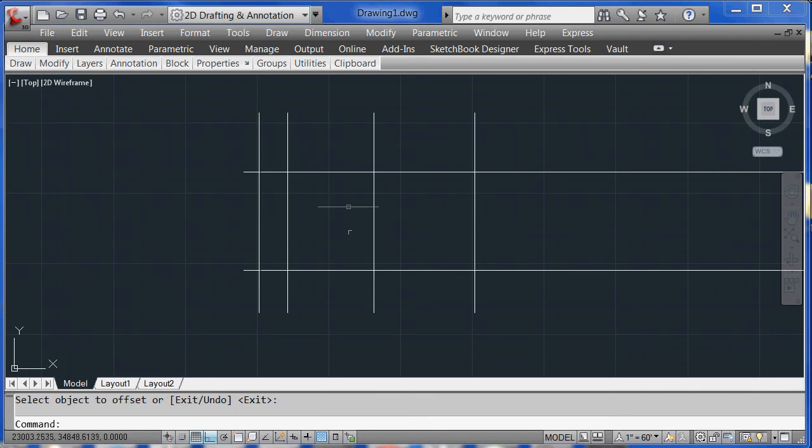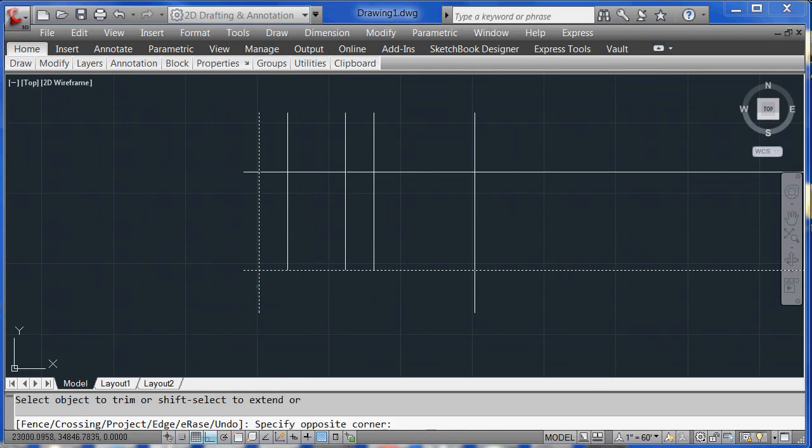Now I have to also place in the wall thickness in here. And that was 1. Okay, and I do that. So you can see how I'm building up this piece here. Now, I do want to trim, maybe, you know what, I don't want to trim these yet, but I do want to trim those on the bottom. So I type TR for trim, and look what I can do. I don't have to necessarily select each cutting line individually. I can just pick somewhere out here in the open space, swoop all these, and then go back in, hit return, and then go back and select what I want trimmed. Oh, missed that one. There we go. Okay, looks a little better.